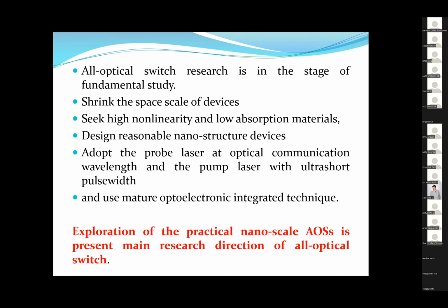In order to realize these technology indexes, we need to shrink the space scale of the devices, then seek high nonlinearity and low absorption materials, and design reasonable nano structure devices. Then we adopt a probe laser at the optical communication wavelength and a pump laser with ultra short pulse width. We have to use mature optoelectronic integrated techniques. Exploration of practical nanoscale all optical switches is the present main research direction of all optical switches.